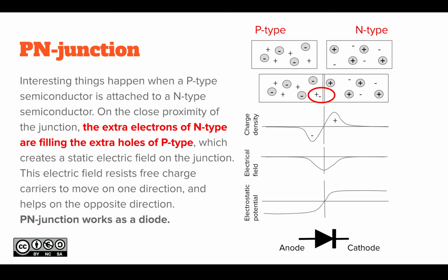And you start diffusing some n-type atoms at a high temperature and in vacuum on the top of it. That basically makes you a p-n junction. So the p-n junction is the place where p and n actually meet. In close proximity, p-type has holes and n-type has free electrons.